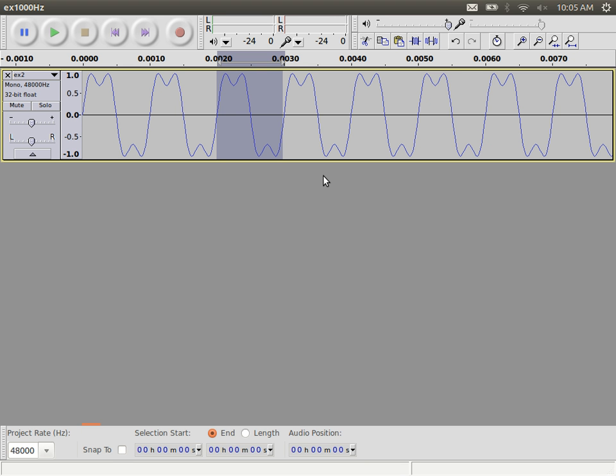The assumption we're making is that at the high point we can transmit 1 bit and the low point represents another bit. Increasing the bandwidth from 2,000 hertz to 4,000 hertz doubles our data rate. That's good. Normally we want a high data rate. We want a signal where we can send the data as fast as possible. We know that if we increase our bandwidth, we can increase our data rate.